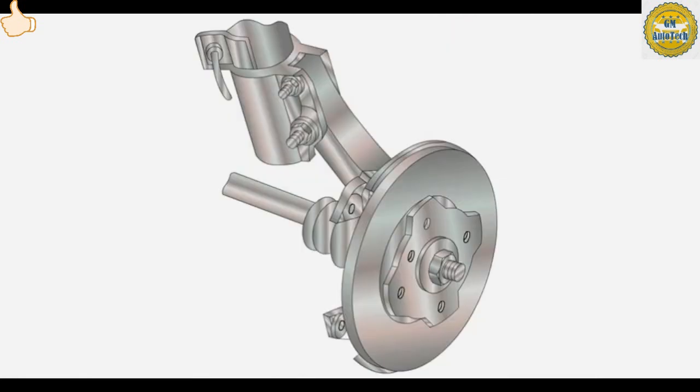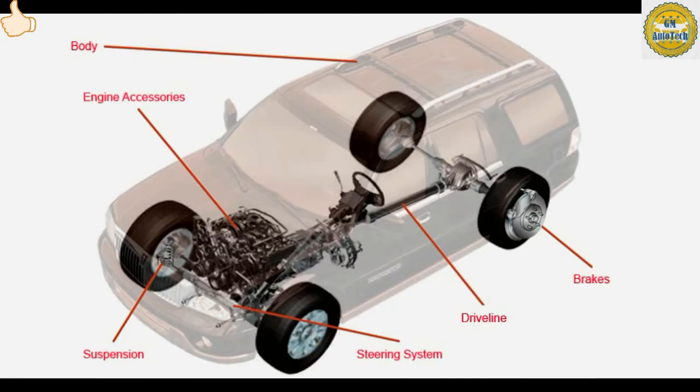Squealing may occur when the disc pads or brake shoes contact the rotors or drums. The noise may go away after a few brake applications. If not, check for excessive brake pad or shoe wear. The thumping noise could be caused by brake rotor or drum runout.